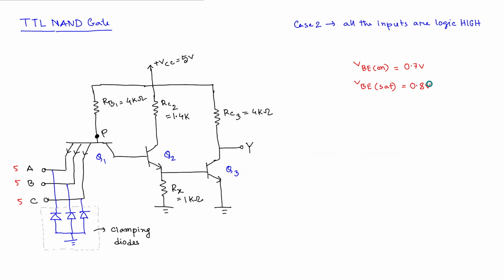because whenever we are talking about saturation and active mode, obviously in saturation mode the base current is higher than the one we got for active mode. You have to understand, because from active mode, as we increase the base current, so does collector current, and that actually forces us into the saturation mode, right? So we also know that if the base current increases, that obviously will also flow through the base to emitter junction, which is a diode. We know that in a diode, if you can increase the voltage across a diode, current should increase. There is a relationship like that, right?